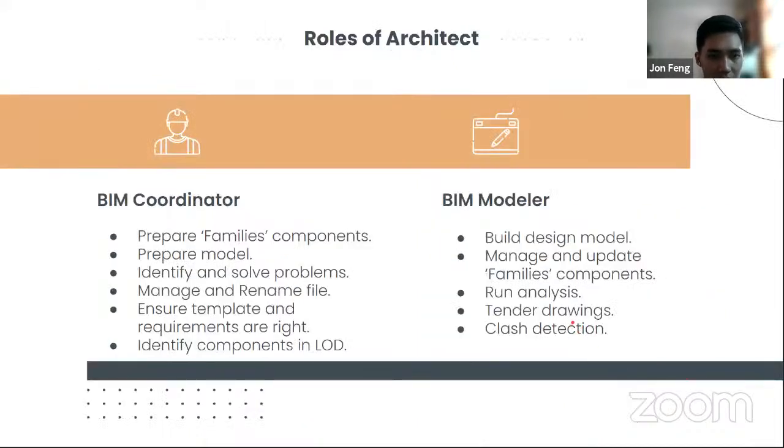Next. Architects will be the BIM coordinator and BIM modeler for this project. The BIM coordinator is to prepare family components, models, identify and solve problems, manage and rename files, ensure templates and requirements are right, and identify components in LOD. While the BIM modeler is to build the design model, manage and update family components, run analysis, standard drawing, and clash detection.